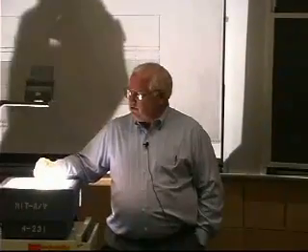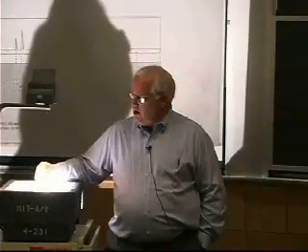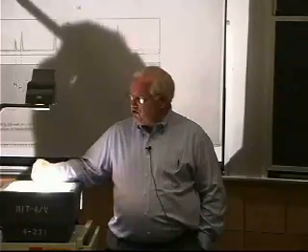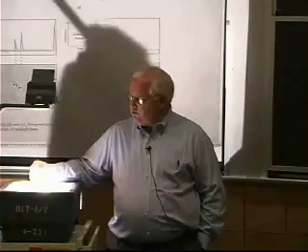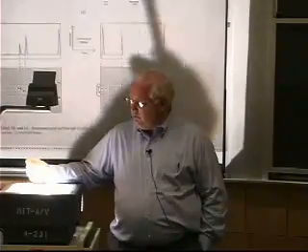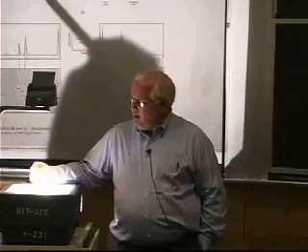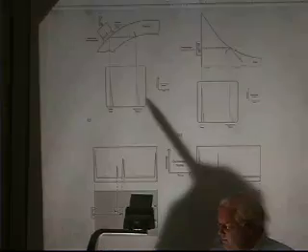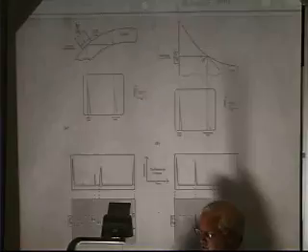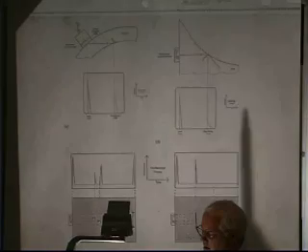So you send out something, and when it hits the other side of whatever it is, you will get a reflection wave back. You catch the wave. So the input pulse goes out. This is your oscilloscope trace. It hits this thing. They're actually showing a flaw over here. They call it the discontinuity echo. Okay, well, there is a discontinuity when you change from solid to air.